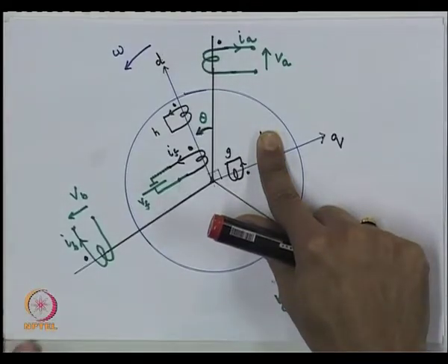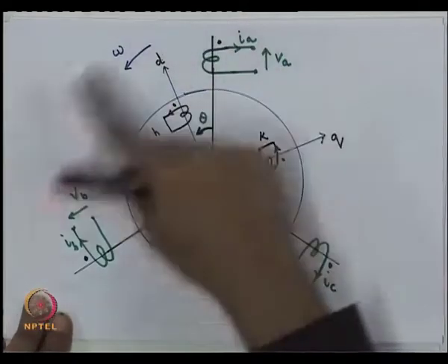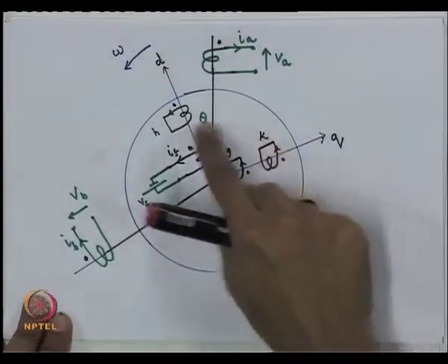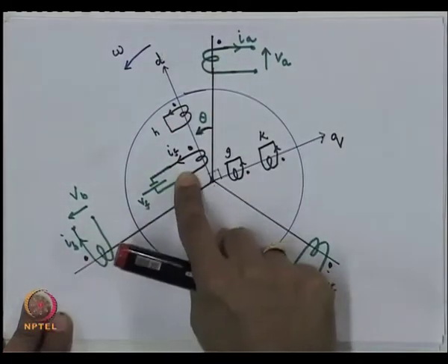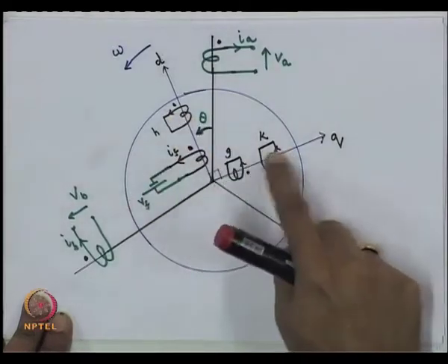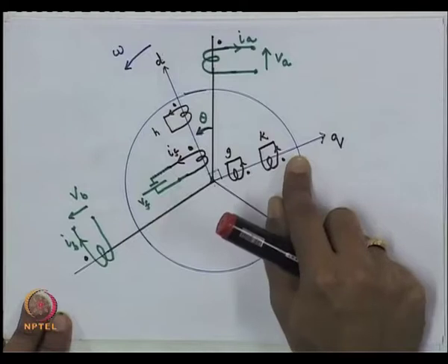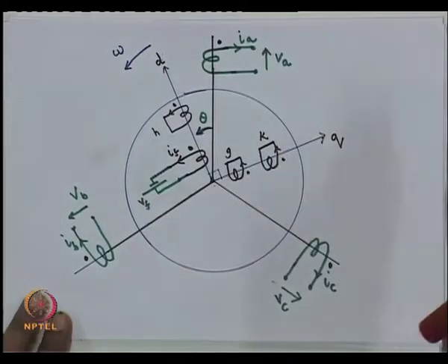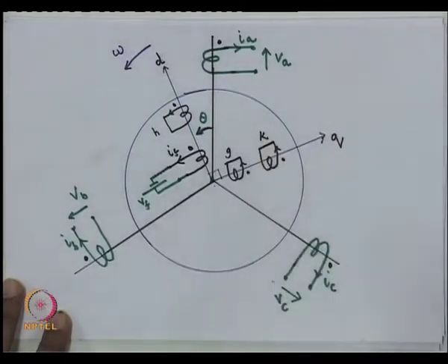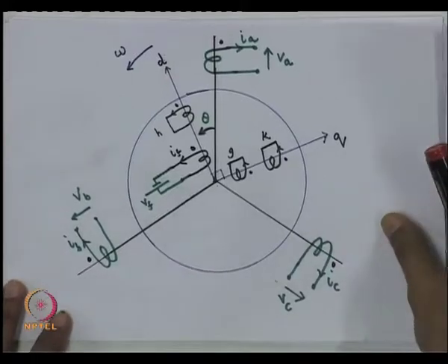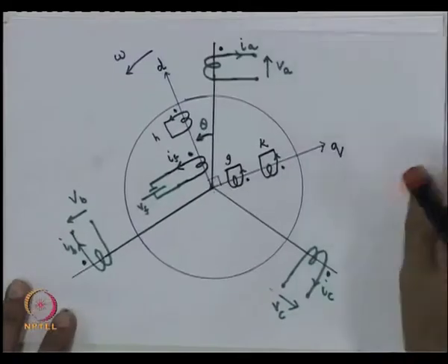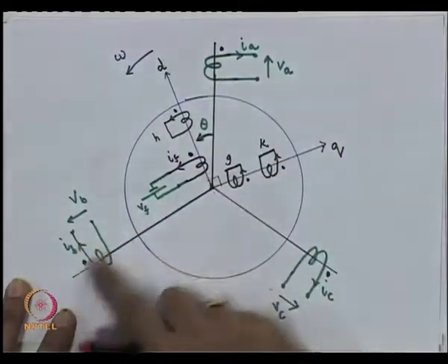Right now let us derive the model for these 3 stator windings, a field winding, and these other 3 circuits which represent eddy and cage or damper winding effects. And then if required later, we can simplify things by opening one of these windings and get a lower order model. But let us initially get a higher order model and try to represent our system. Remember, of course, that when I say that this is a winding, this is a schematic representation.